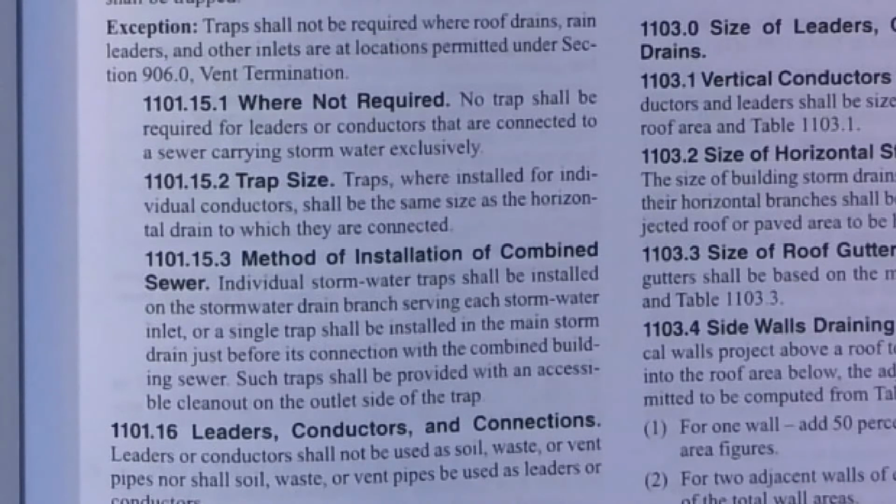Once I go horizontally, I may have to increase my pipe size, because I can handle a 4-inch volume vertically, but once I go horizontally, that 4-inch volume cannot stay maintained and it'll start to back up. So we have to upsize the horizontal. The horizontal piping is always going to be larger than the actual roof drain body itself. Not always, okay, but it'll never be less, I'll tell you that.